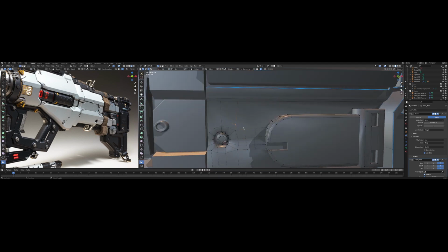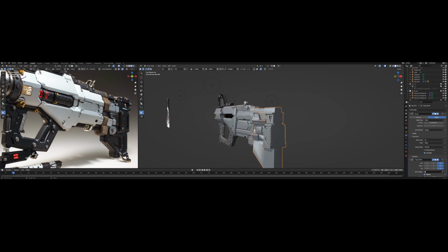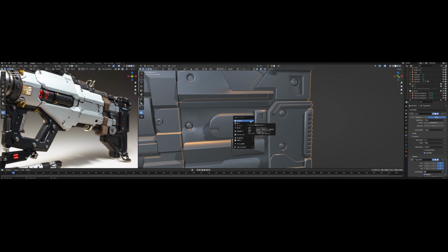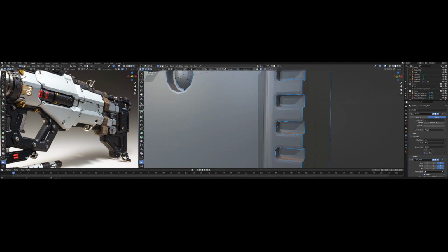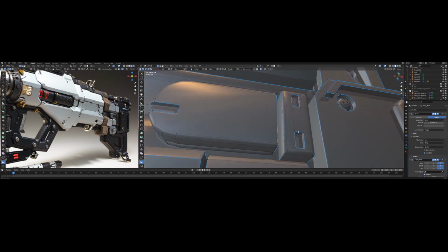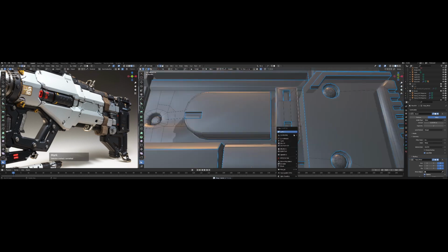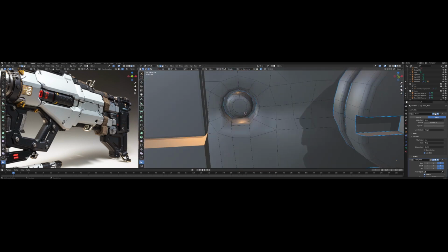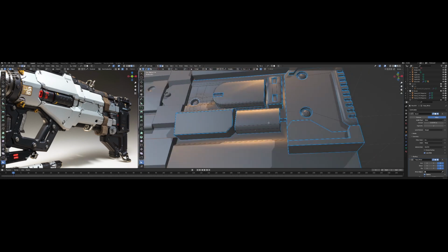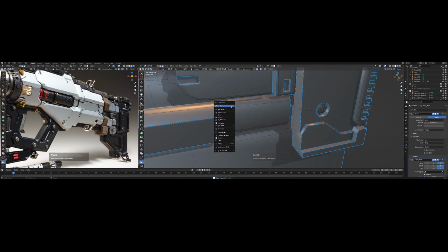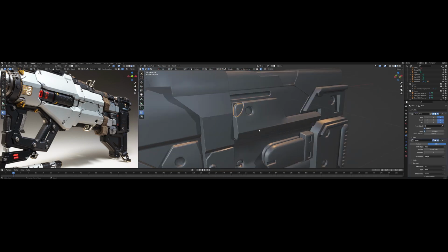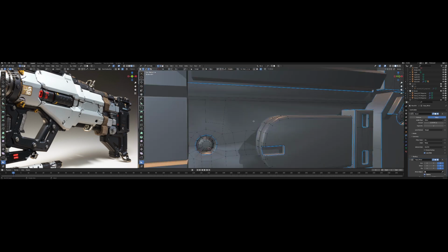I just want to give another idea: you can still use the automatic sharp, but you'd better change the sharpen angle to be much larger, for example 60 degrees. Even though there will be a lot of areas that you do not want marked as bevel edge weights, they won't be marked with the bevel weight either. So you do not need to do some extra work for it, right?